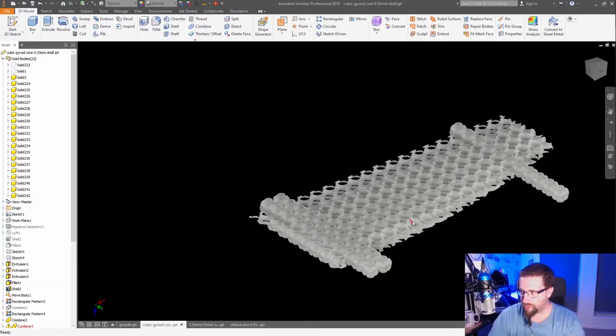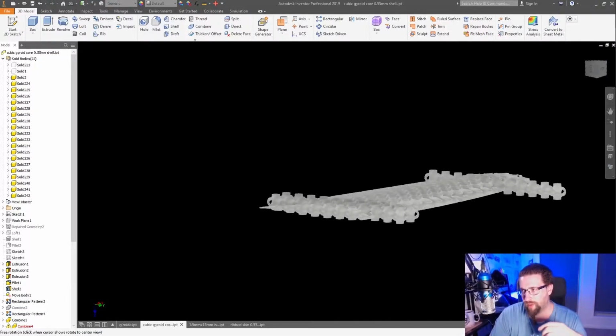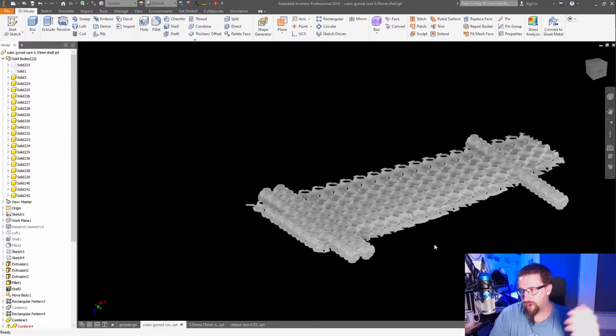If these were microstructures like a sponge, with tiny little holes, and the wall thicknesses were at the very resolution limit of the printer, and you scaled the thickness of the walls for the gyroid to the size of the pattern, and the volume and density of the pattern, to the point where it was optimal, you would end up with a resin sponge that would not necessarily add any structural value or strength to the part. So yeah, we're just going to say no. The gyroid's out of the picture.